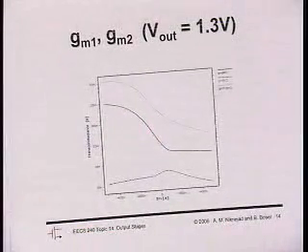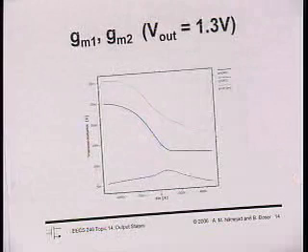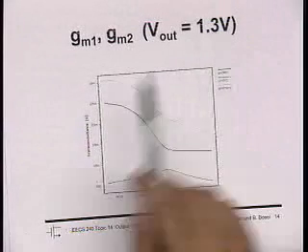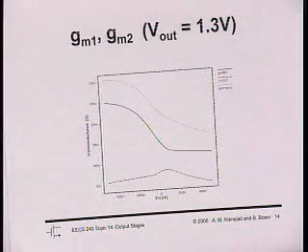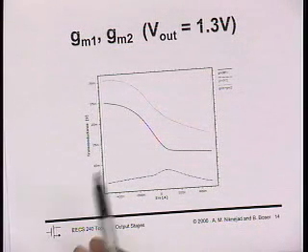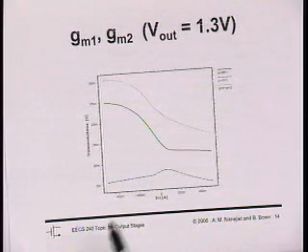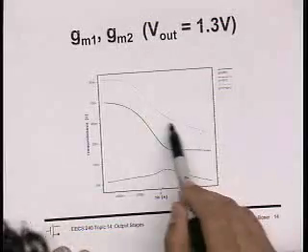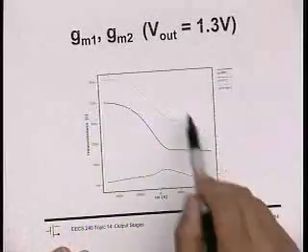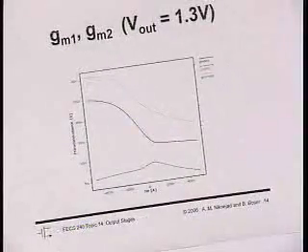The other issue to look at is, again, the GM of the device with the output not at mid-rail. If you have the output close to one of the rails, then again you get this asymmetric situation. You have to be careful. Now you can see that the sum GM, which is this top curve, is varying a lot. And so again, you can get into an instability region.